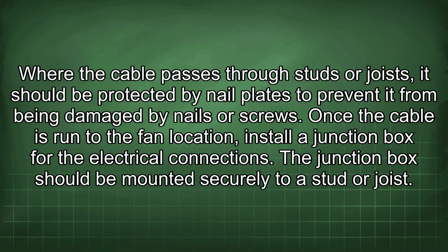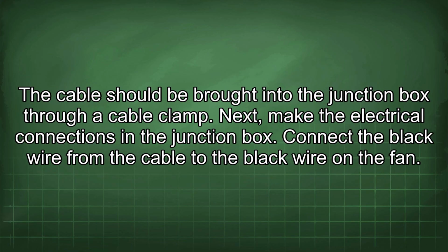Once the cable is run to the fan location, install a junction box for the electrical connections. The junction box should be mounted securely to a stud or joist. The cable should be brought into the junction box through a cable clamp.